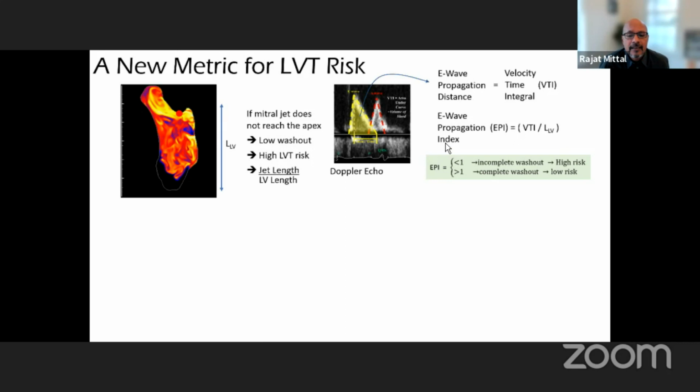The first part of the question: in blood simulations, we have modeled blood as a continuum, but there are groups that are trying to, once you get to very, very small capillaries, then you cannot ignore the fact that blood is made of cells. So there you have to go into cellular-level simulation. But a left ventricle is very big. There are billions and billions of blood cells, and a lot of plasma. So there the blood definitely acts like a continuum, and about 90% acts like a Newtonian fluid. So we are able to get away with those assumptions.